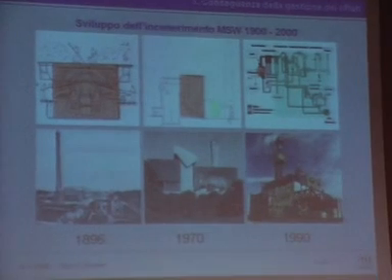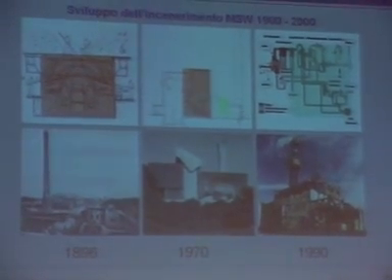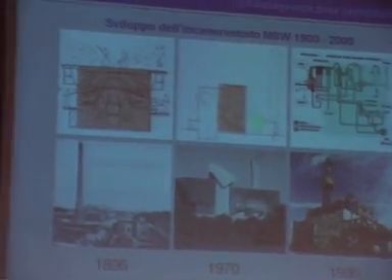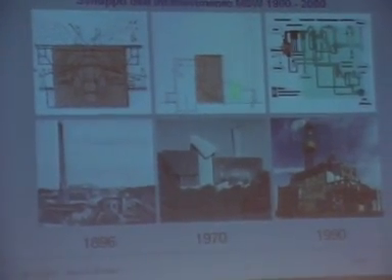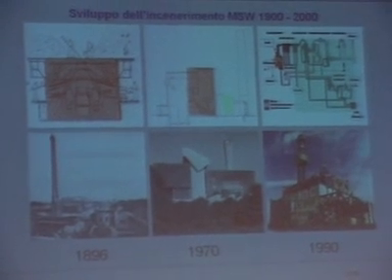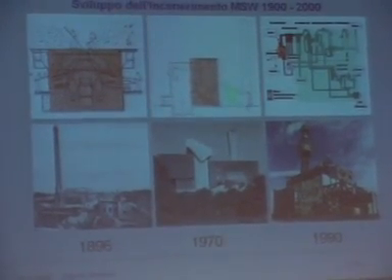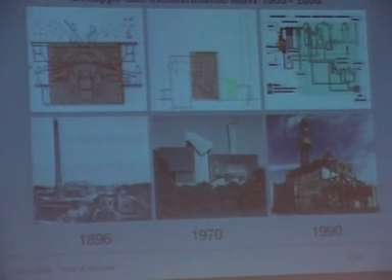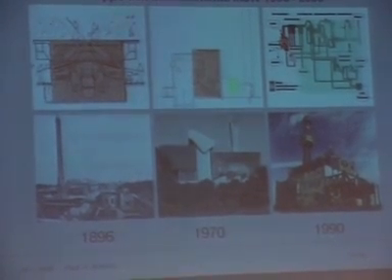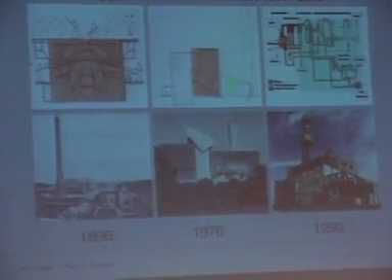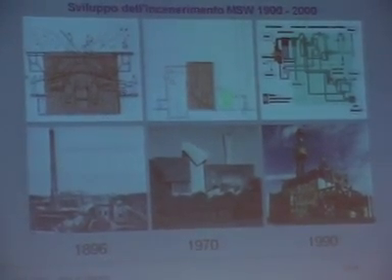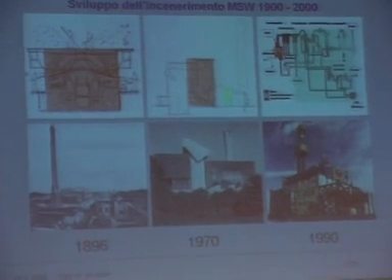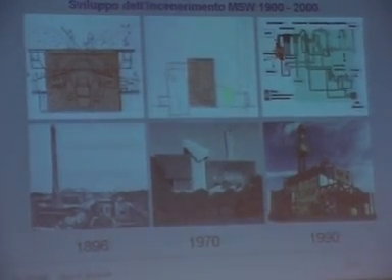In 1970 there was a very small electrostatic precipitator, which usually was empty after maybe 4 or 5 months, because corrosion had really destroyed this electrofilter. And on the right-hand side you see 1990, a municipal incinerator consisting practically only of air pollution control devices. The furnace is actually very small. Of course, this also has some impact on the cost of this technology.